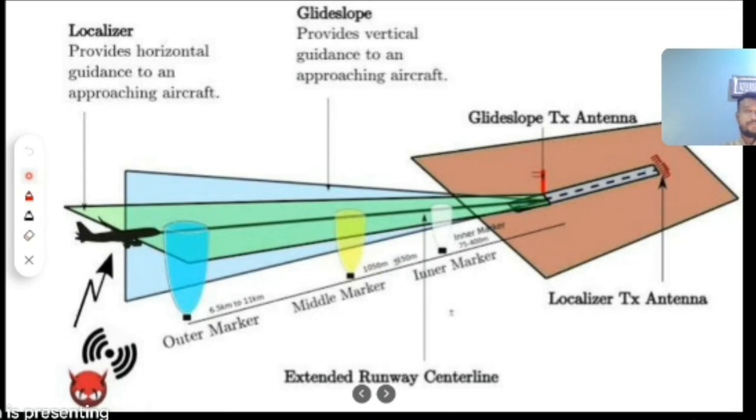Ajay, what is the doubt here? Okay, suppose Ajay, you are sitting in this aircraft, flying, coming for landing. You just reach the outer marker. You will hear a dash dash sound in the cockpit. That means you will know you are almost 8.5 kilometers away from the runway, right? The moment you cross it, you will not get anything. That means there is no distance indication here, correct?